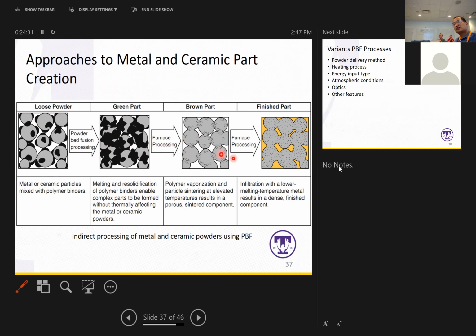And this kind of process actually gives you the basic concept for many of the new approaches, like the one Desktop Metal did. And also there are some stereolithography based approaches. They could build ceramic parts using a similar concept. They use polymer binder to bind the loosened particles together, and then go through all the following processes to solidify the parts.